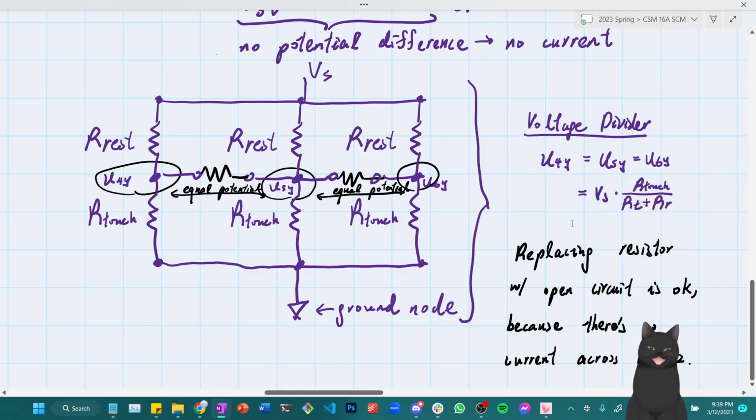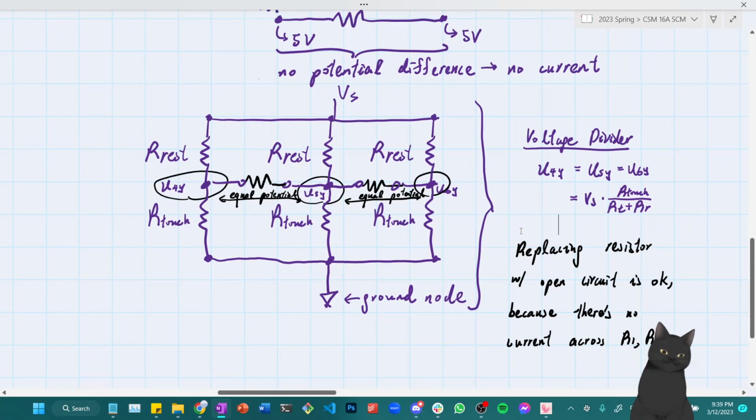and thus not every node has the similar voltage. And because not every node has the equal voltage, you will not have equal potential across each node, and you will have current flowing through the resistors R1 and R2. And since there is current flowing through R1 and R2, you cannot model them as open circuits. So hopefully going reverse in the direction helps you understand the question a little more and what it's asking.